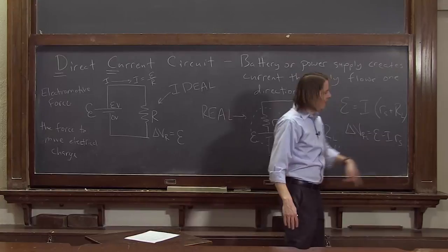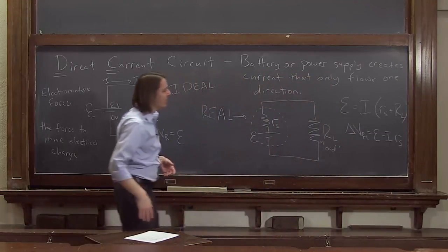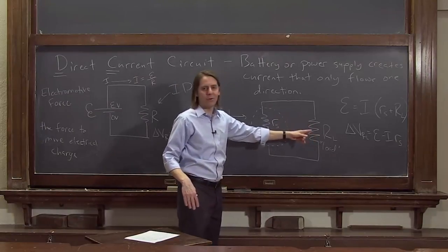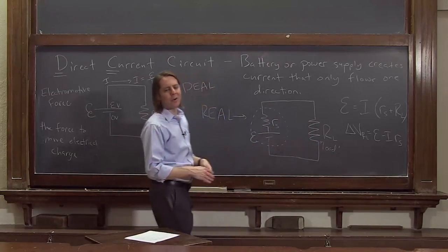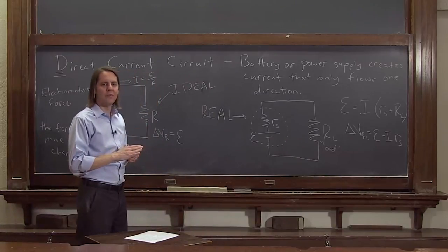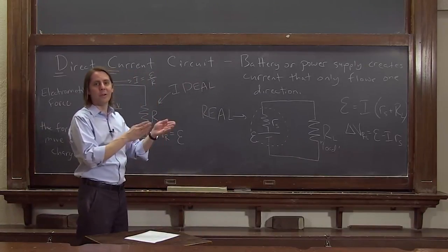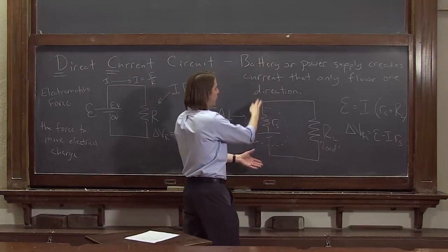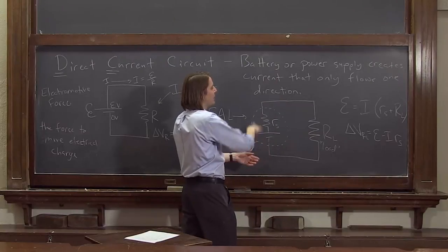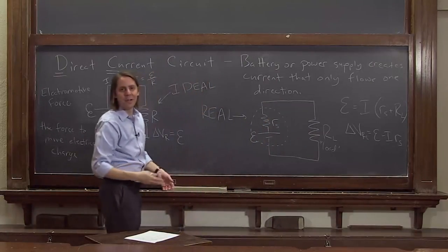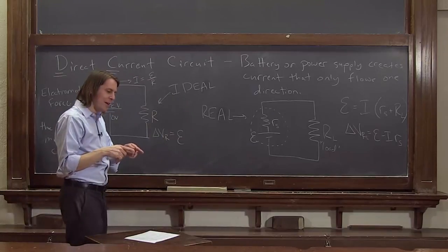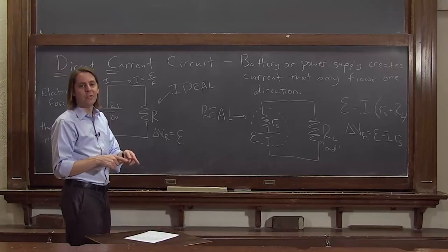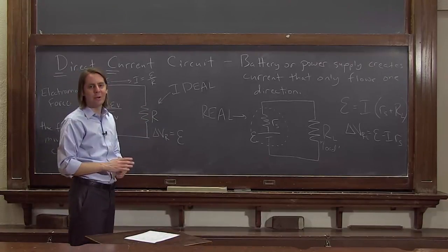See? It's not a constant amount of voltage you lose. The amount of voltage drop you lose from the battery depends on how much current is flowing, which depends on our load. Okay? So no power supply or no battery really is a truly constant source of EMF. It actually depends on what it's doing. When you just have a battery open to the air and R load is infinite, you get no current flow, and then you get the maximum. You do get the EMF. But when you're actually running a circuit, that EMF goes down. So if you have a battery or power supply and you measure its voltage with some really high impedance meter, you get a high voltage. When it's powering some circuit with a lot of current, it actually might be lower.